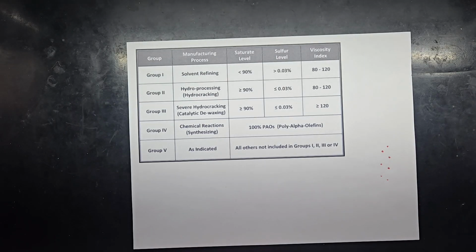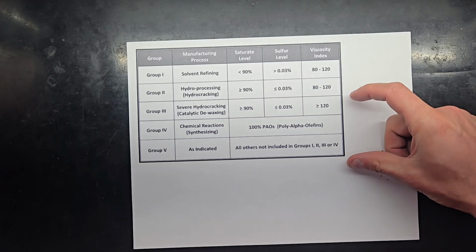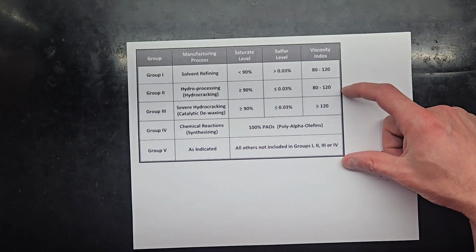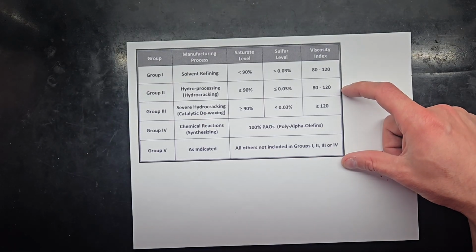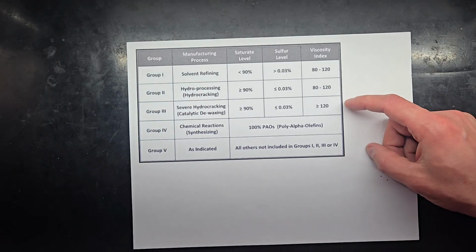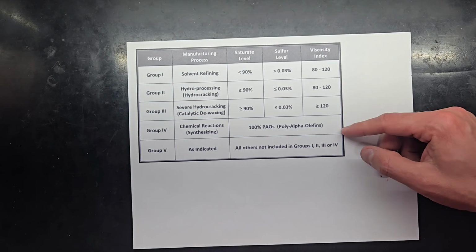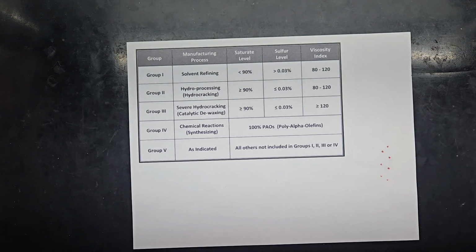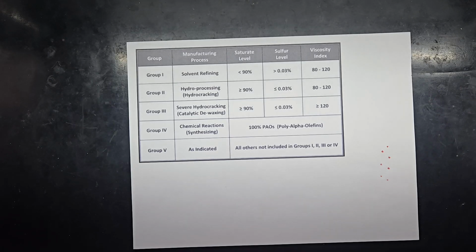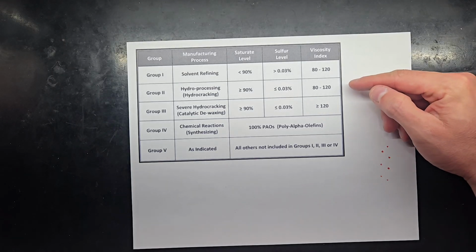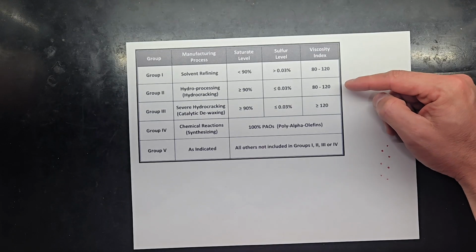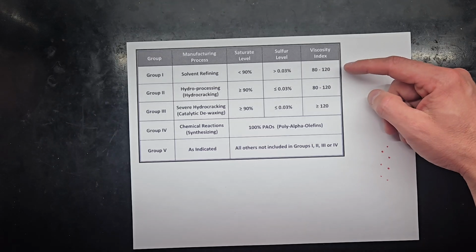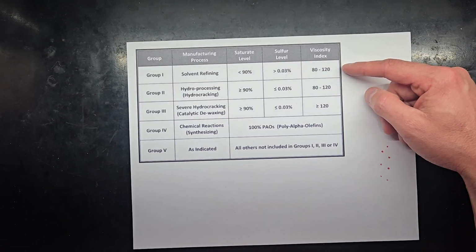And so I want that to sink in for a minute: when you're buying an engine oil that says it is a fully synthetic API SP engine oil, it can be manufactured from any one or any mix of these 3 groups of oils. If you're buying a conventional engine oil, it's more typically going to be a group 2, and I believe some of the gear oils are actually made from group 1 base oils.